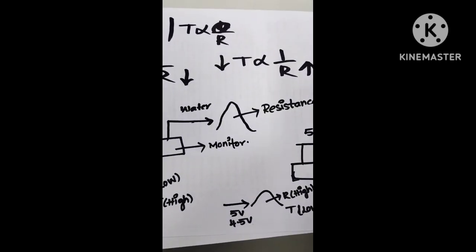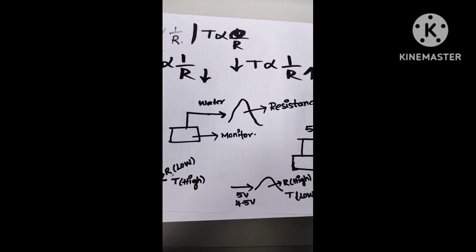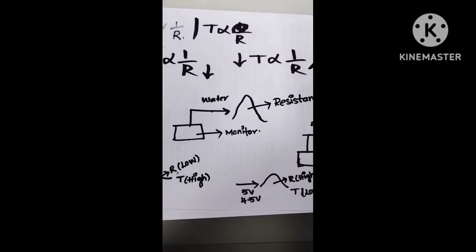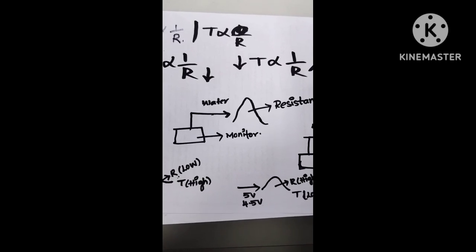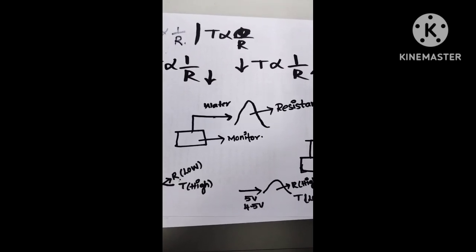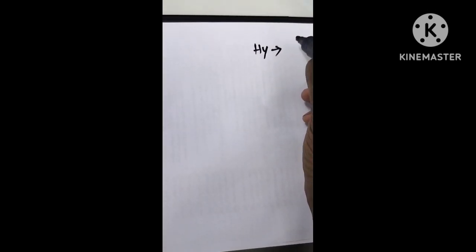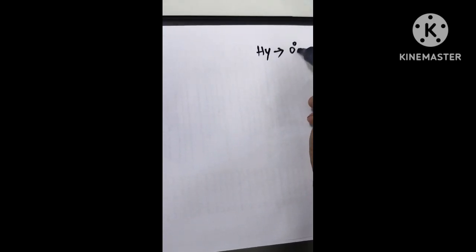For further proof of this, I will show you. I'd like to come to the machine, and then I will explain. For this I'd like to use the data of the engine computer. When I open this engine computer data, it is showing the hydraulic oil temperature sensor at 0 degrees.